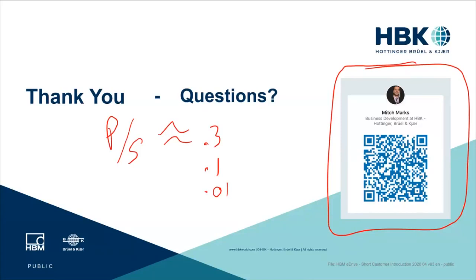All right. When would I use a fundamental versus a full bandwidth RMS calculation? Yeah, so that comes down to what you are trying to compare to, what you are used to, and what you need to look at. I don't think there is necessarily a right answer. I prefer the wide bandwidth value, the full harmonic content, because you can always filter down and look at individual things if you want.